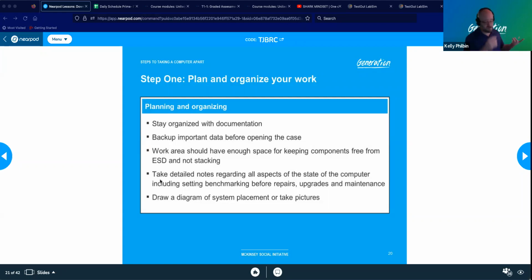The other thing you can do is draw just a rough outline of what the device looks like, a rectangle. And then if you remove a screw from the upper left-hand corner, you draw a circle on the page and you put the screw in that little circle. You can just draw little circles on a piece of paper and put the screws in those circles, and that'll tell you where they go when you come back. Those are 2 simple ways you can do what they call screw mapping to make sure you put the screws back in the places where they came from. Questions on this?